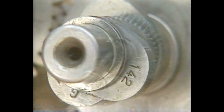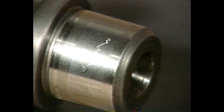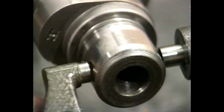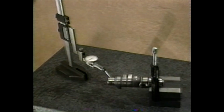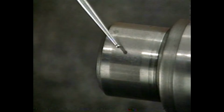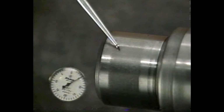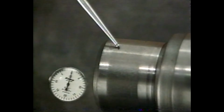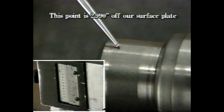For cam shapes where the lobe ramps cover more than 180 degrees of cam rotation, the only diameter that can be measured directly is that of the camshaft bearing surface, which is on the crankcase end of our camshaft. This is measured with a micrometer to be 812 thousandths of an inch. We will use this bearing surface as the reference for deriving the base circle diameter. We position the needle of our test indicator on the highest point of the bearing surface and zero our dial indicator to this point. From the vernier scale of our height gauge, we find that the top of the bearing surface is 2.990 inches off our surface plate.